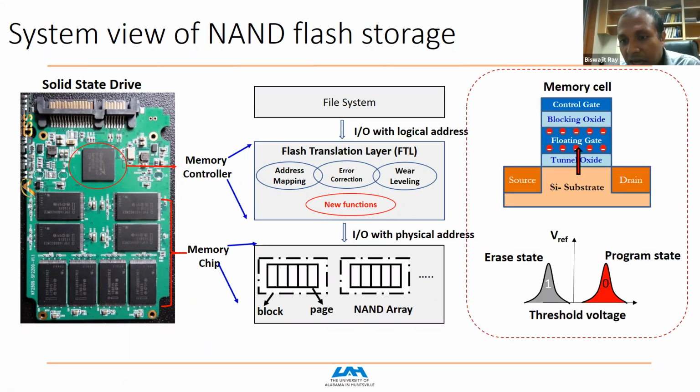And if you look at how the memory controller interacts with the chip, this is a good diagram of how you read, for example. You have certain bits that are programmed. That means they have electrons on the floating gate. And the moment there are electrons on the floating gate, its threshold voltage will be higher, right? So this plot below is showing the analog threshold voltage distribution.